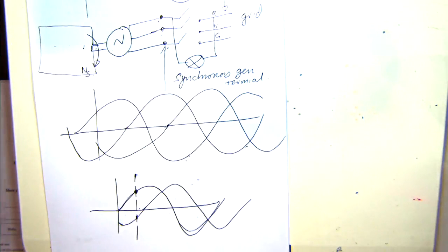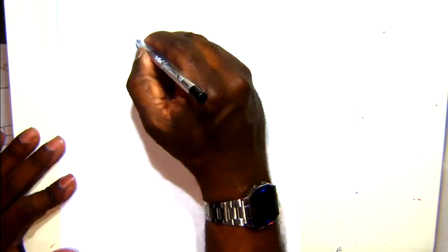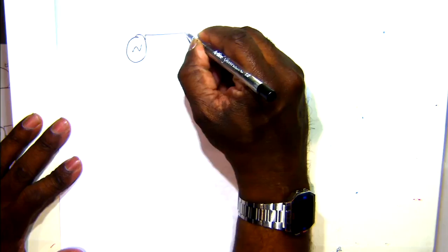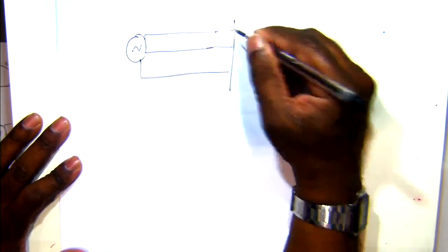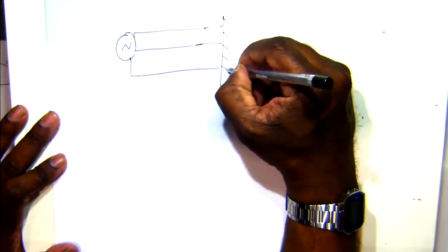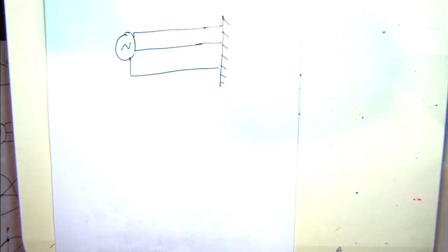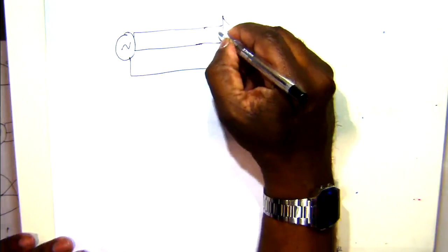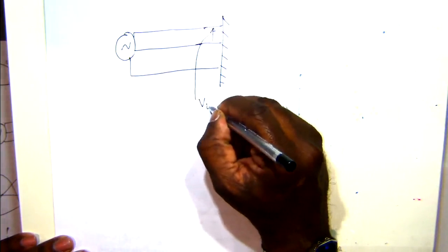Once you've synchronized it, you have two parameters that you can control. Let's say you've synchronized the synchronous generator to the grid. So now it's connected to the synchronous grid. Usually we draw the grid like a bus like this. This is a fixed voltage that doesn't change. The grid is huge. The variation of grid voltage we can't control. That's a property of the grid. And then this voltage is fixed. That's the terminal voltage, let's say VT. That's fixed.